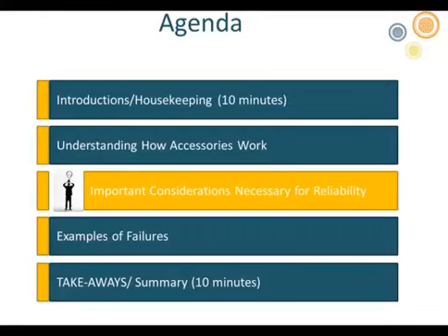Yeah, and like I said, most utilities use 100% because typically their systems are hard-grounded Y systems, and they're going to clear the fault right away. And because they run so much cable, they don't want to pay for the extra insulation that would be needed for 220 versus 175 mils for 15 kV cable. 220 mils is typically your 133% level for 15 kV cable, and 295 mils is 25 kV insulation or 28 kV cable rated insulation.